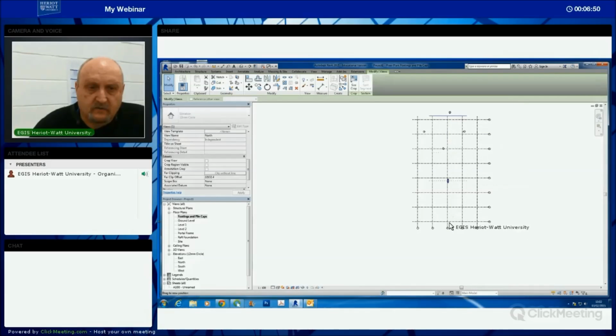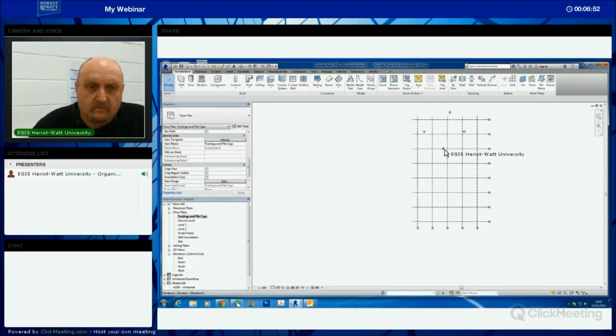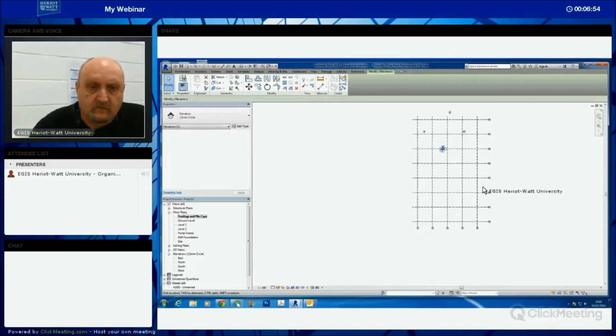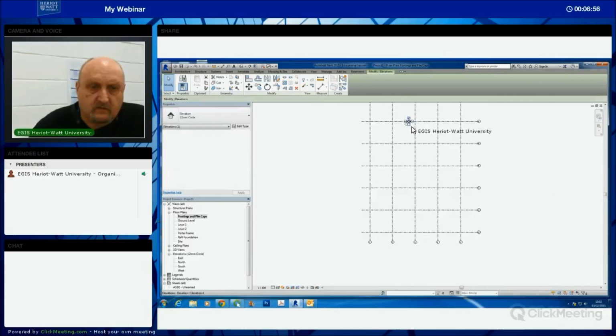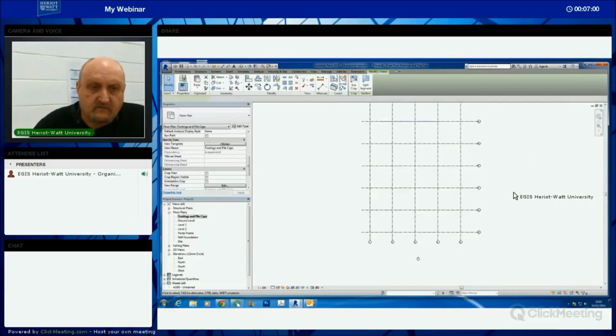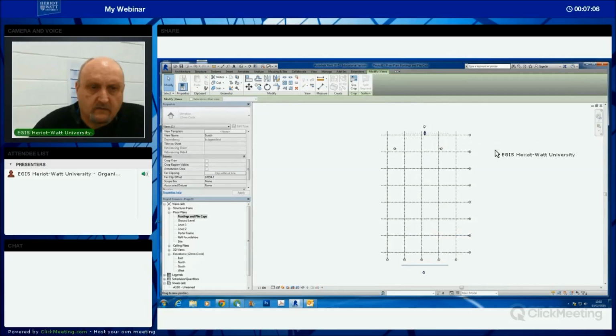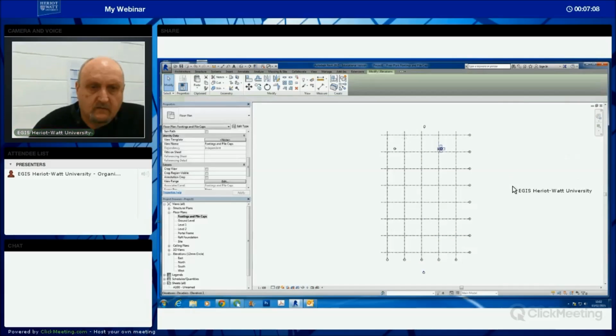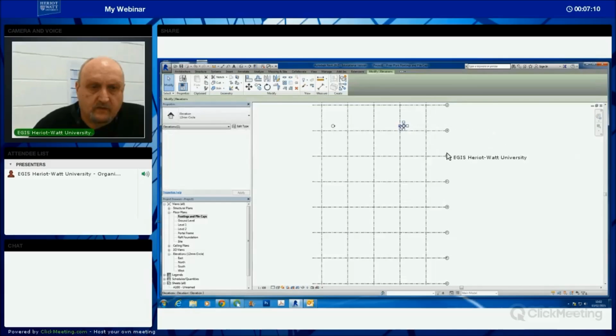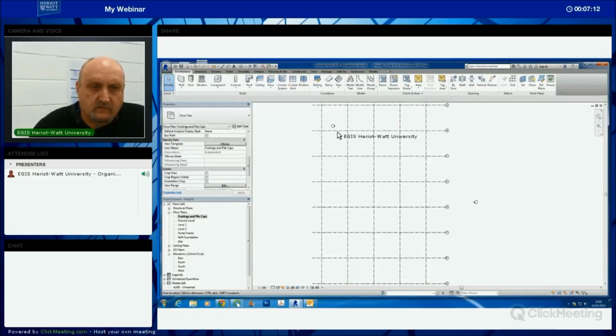So I drag this one down, and here I'm going to move this by clicking on the fat bit. This is south, obviously. Click on its nose to set the view range here, the clipping view, and up here like that. East here, move it into the kind of middle somewhere, just a wee bit random.